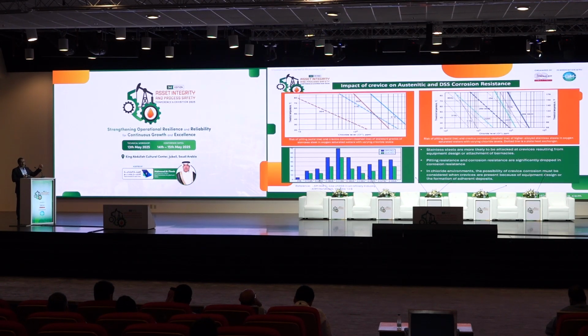You know that many of the materials have a higher tendency to be attacked under crevice corrosion compared to their condition without crevice. This simple graph shows the tendency of some of the stainless steel grades, including austenitic stainless steel, duplex stainless steel, and the special high austenitic stainless steel alloys, between the normal pitting attack resistance and the crevice resistance. There is a major difference between them.